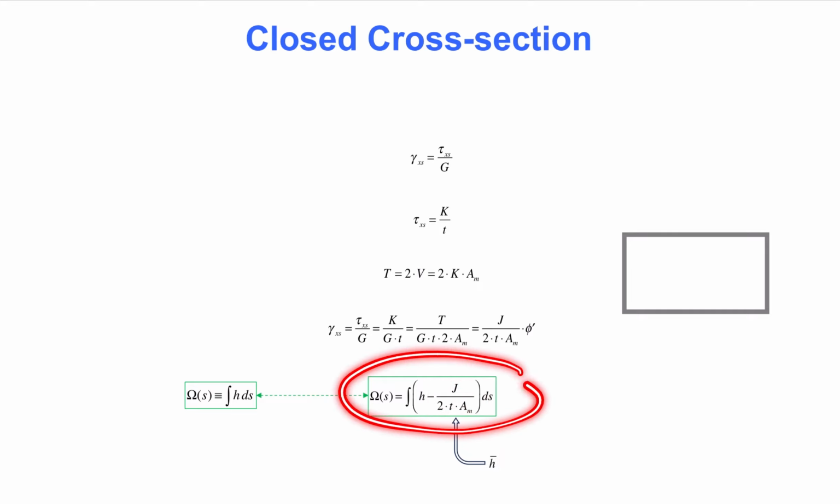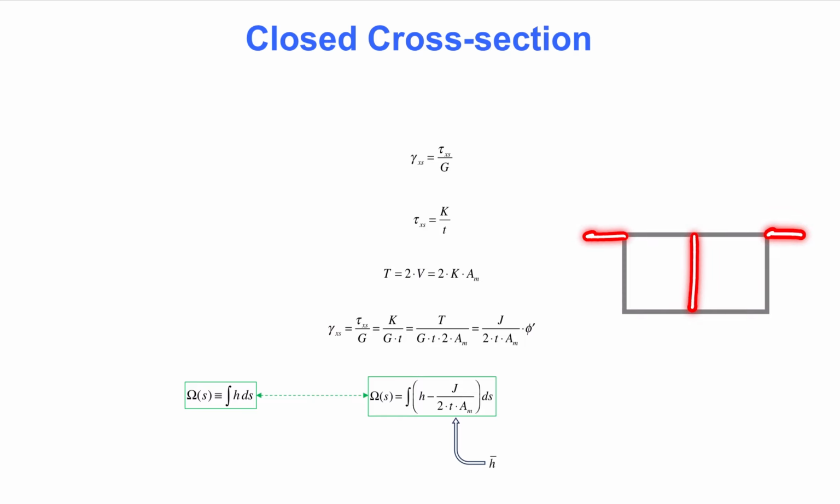A few additional considerations are necessary for cross-sections with more than one cell and potentially free flanges. Although this video does not address that problem, the note on warping torsion posted at terje.civil.ubc.ca Toolbox and the examples of cross-section analysis posted on the same website show derivations and practical applications for multi-cell cross-sections. In this video, we have now established all the ingredients of the boundary value problem for unified bending and torsion of thin-walled cross-sections, with emphasis on the new quantity that we call omega.